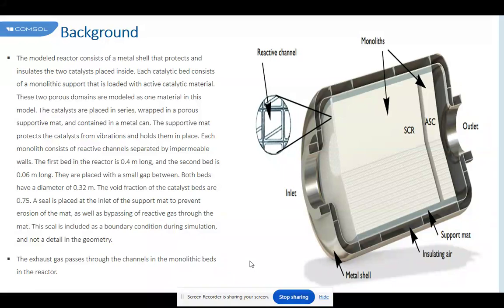In a separate study, Ramanathan and his colleagues in 2004 also presented simulations of the transient behavior and showed that for the case of back-end ignition, the cumulative emissions may be lower for metallic monoliths. However, for the case of front-end ignition, the light-off time is shorter for ceramic monoliths, leading to lower cumulative emissions compared to metallic monoliths. These, as well as other prior modeling studies in the literature, were mainly concerned with emissions from automobiles.